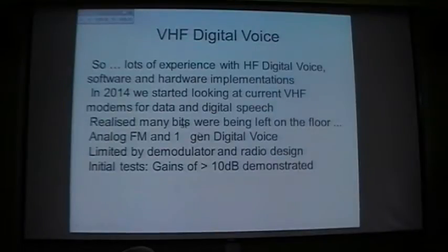What I mean by that is that due to the design of the modem waveforms and the implementation of the modems, we were wasting a lot of power that was being used to send both data and digital voice over the VHF radio. I have a background in satellite communication where every fraction of a dB counted. If we built a modem and it wasn't within 0.2 of a dB of theoretical, we'd get sent back to do it again. So I nearly fell over when I found that some of these modems were losing 7, 8, even 10 dB, what we call implementation loss of the modem.